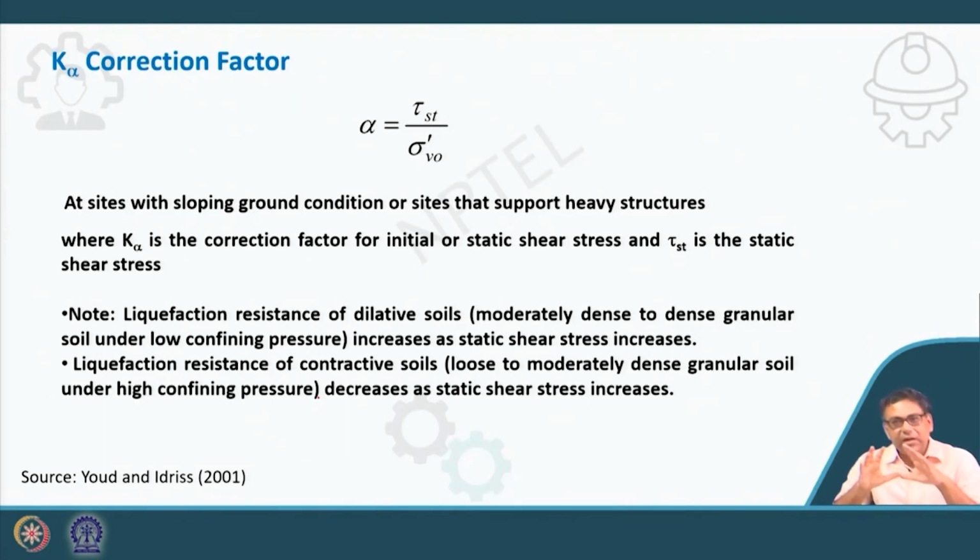But in the field, if there is sloping ground, there is already a static shear stress. So during shaking, the shear stress that develops is just the cyclic shear stress. If static shear stress already exists because of a foundation or buildings, that will also have an effect and it will reduce the factor of safety.